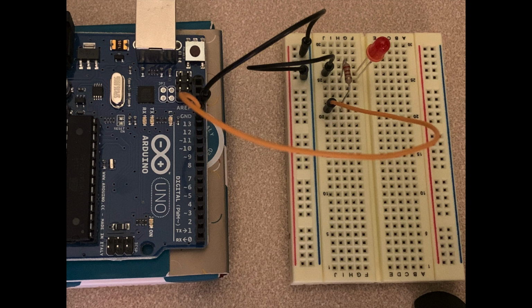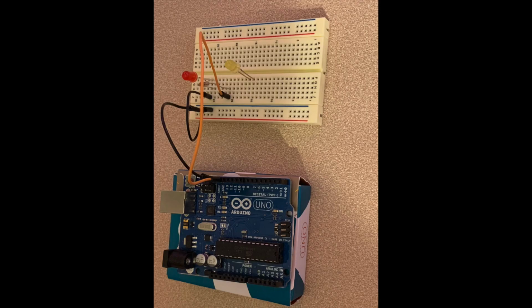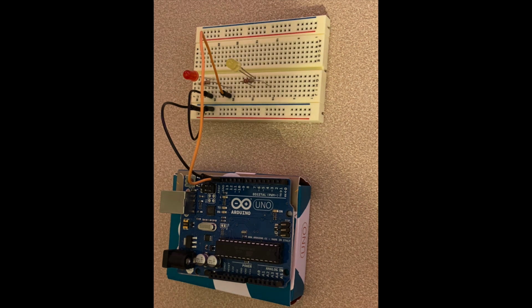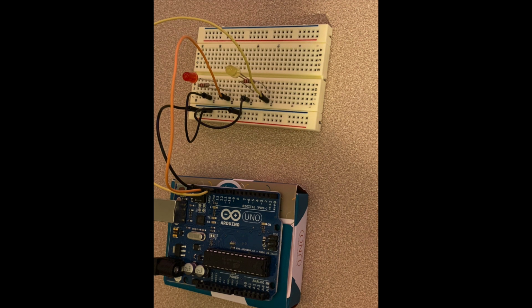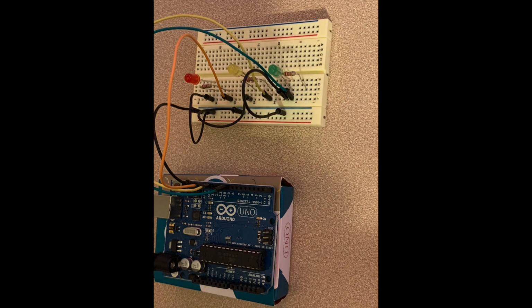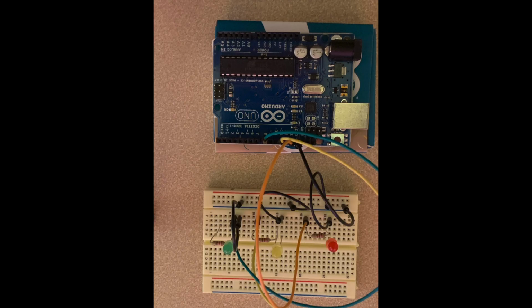Now that we understand how this circuit was wired, let's go ahead and add 2 more LEDs while we're here. I'll start by inserting a yellow LED into the breadboard. Then I'll add another 220 ohm resistor in the row with the LED's positive lead and connect the other end of the resistor to digital pin 12 on the Arduino with a yellow wire. And finally, run the negative lead of the LED to the ground rail on the board. Then I'll add a green LED following the same circuit configuration with a green wire running to digital pin 8 on the Arduino. Now let's go back to the sketch and make some mods.